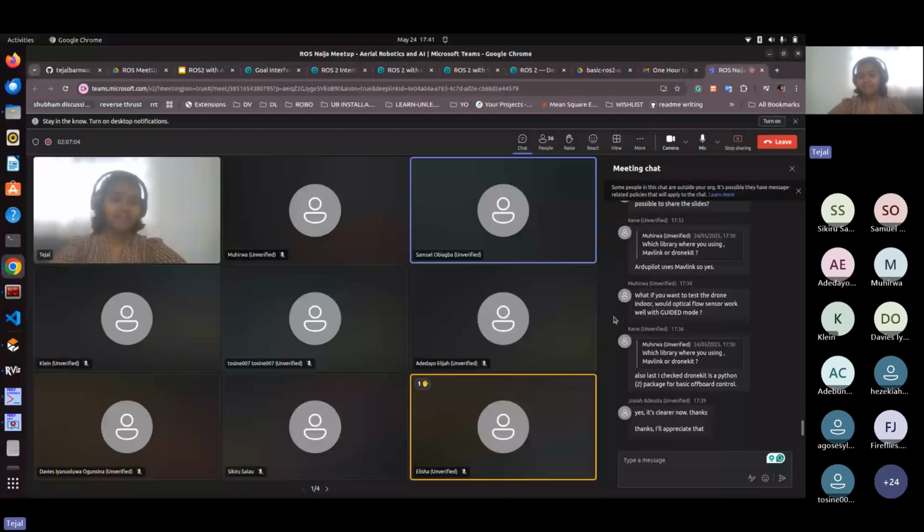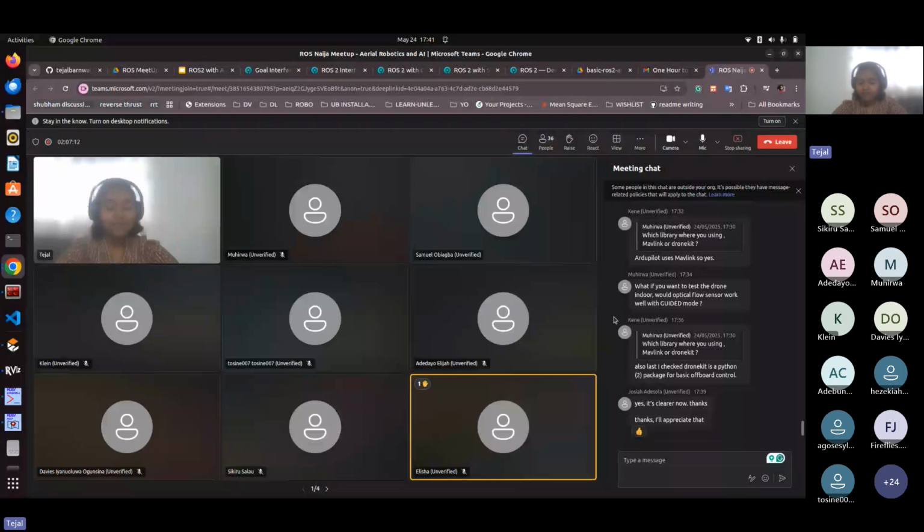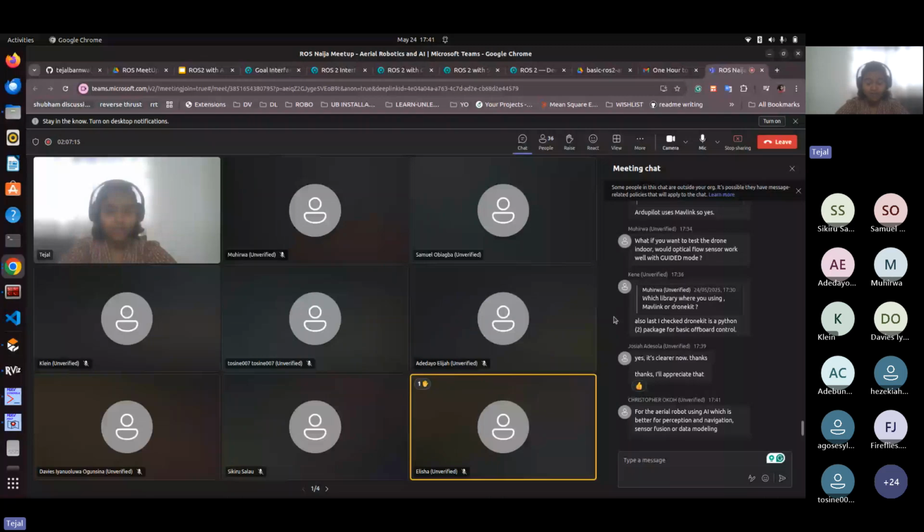Yes. So we have experience working with optical flow sensors. Generally good optical flow sensors come with their own IMU and distance sensor with a small camera also, where the distance sensor ranges from 10 meters to 30 meters based on its range.